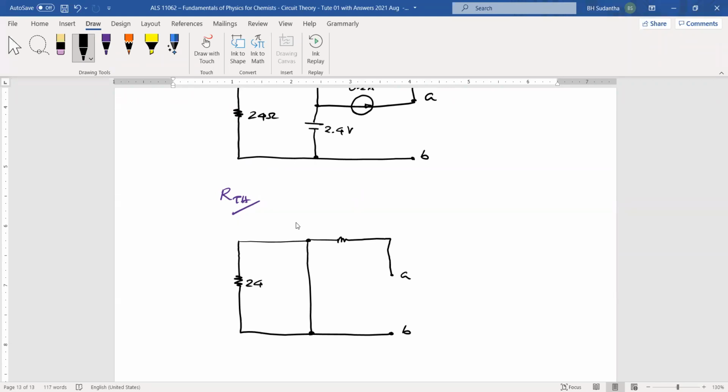And this is 24 ohm resistor and this is 16 ohm resistor. We have to look at it from this side to find RTH. This is a conductor parallel with another resistor. Then current will not choose this path. Then effect from this 24 ohm resistor is 0. Then the final resistance of this RTH is only this 16 ohm resistance.